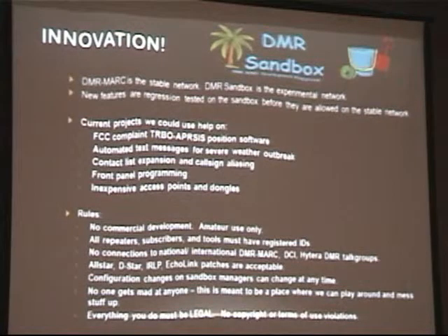Yeah, go ahead. What is call sign aliasing? That's a good question. Well, in most of the commercial formats, the unit ID is a number. That's what Doug assigns. So if you've got a radio and you want to put it on the network, you get a number. That's your number. It's like your phone number. But your caller ID, if I dial your number, it shows, so that's an alias. It's a name or other information like a call sign that's associated with the ID number. And you can put that in here, so when Frank talks, it can say Frank or no good scoundrel or whatever you want it to say. Okay. Thank you.